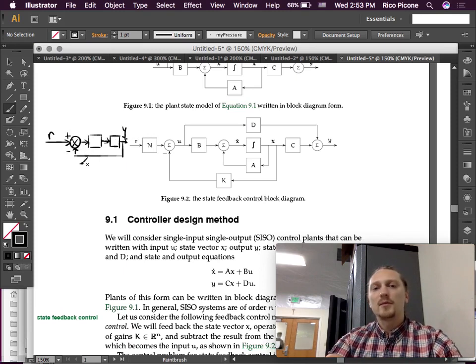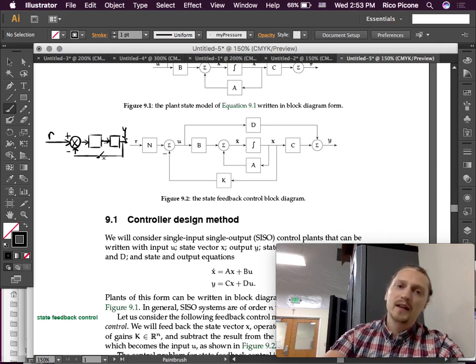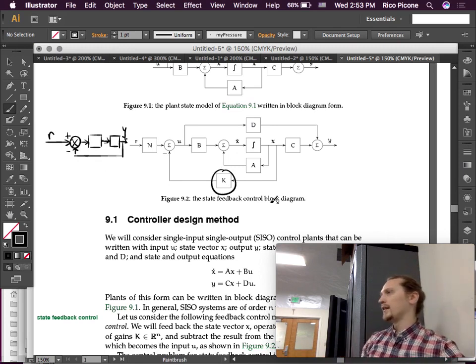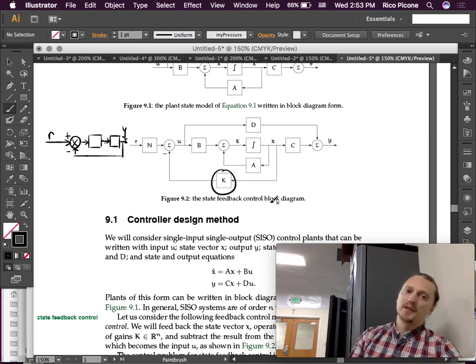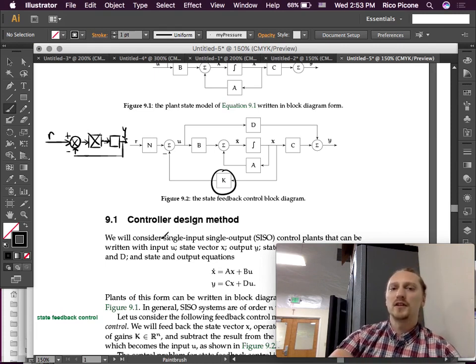That's what our controller loops always used to look like. Now we've got non-unity feedback, first of all, but we're putting not just any old transfer function there. That's our gain transfer function. So we're putting in a vector of gains in that feedback loop. And that's where all of the control happens. So we don't have a controller here at all anymore. It's just the gains that go back through here.